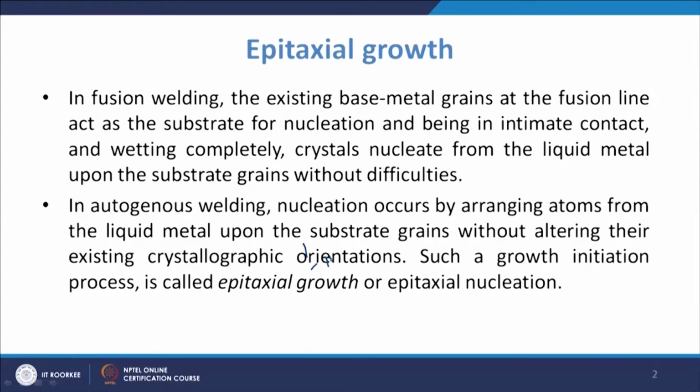Now, in those cases you will have growth, and typically what you see in welding is that if you have similar material which is present and acts as the nucleation sites, then further and further growth takes place. That is the case of the epitaxial type of solidification or epitaxial growth. That is how it is defined in such cases.